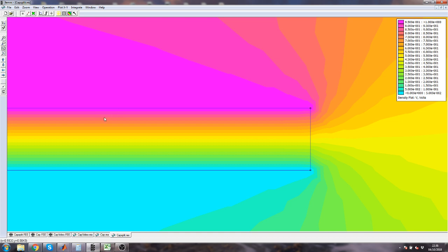sort of linear graduation of the voltage, whereas as we get towards the end, because there's no plate here, the electric flux is not bleeding as such, but there are these fringing fields which exist because the geometry has changed, and our parallel plate assumption doesn't take account of this bit.